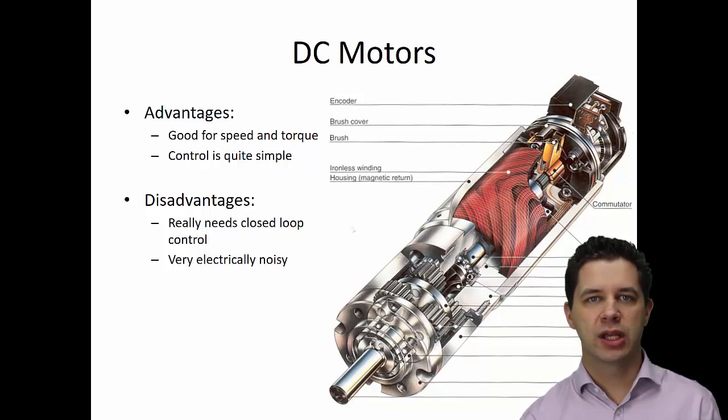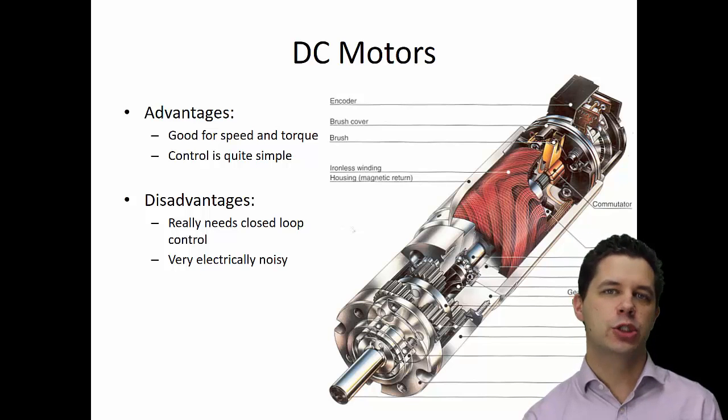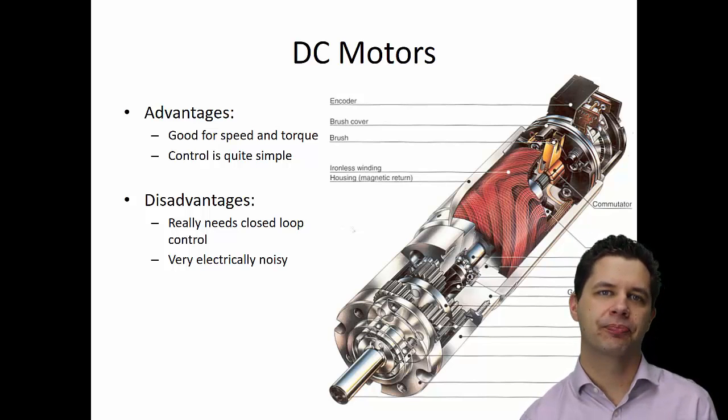In terms of advantages, they're pretty good for speed and torque generally, and they're very, very simple to control. Essentially, if we only want to drive in one direction, we just need a single FET or something like that to drive it, or otherwise an H-bridge to drive it in forward and reverse direction.